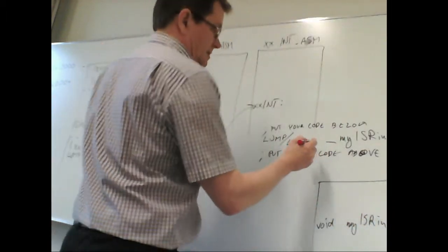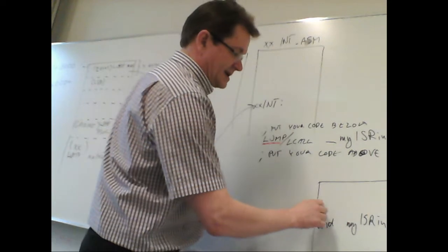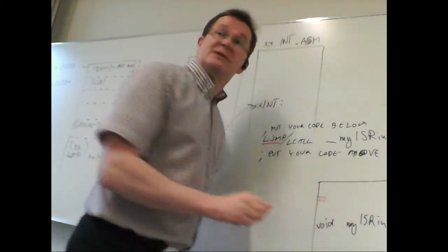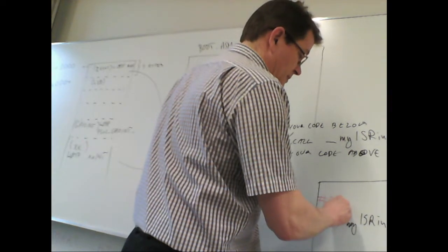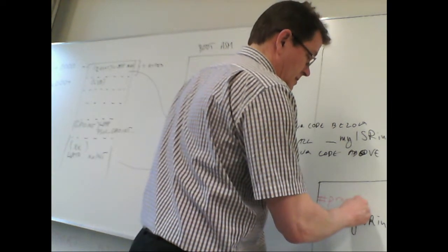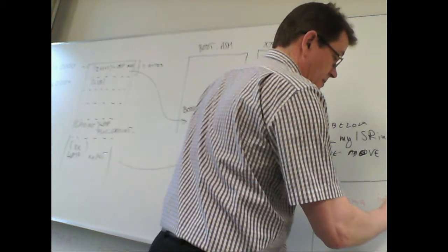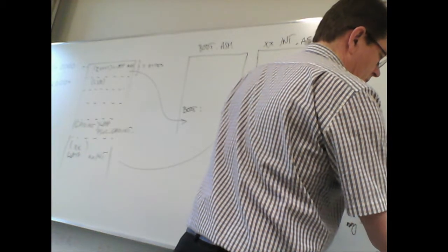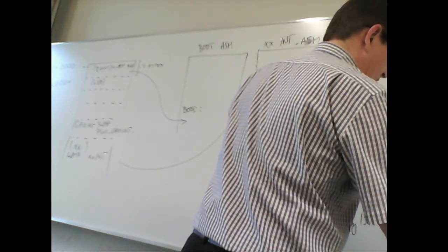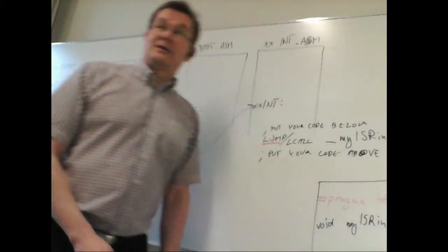So if you are using long jump, then you must have a pragma statement, which is again a compiler directive for extra stuff. Pragma interrupt handler and then the name of that function. It doesn't fit in here anymore.